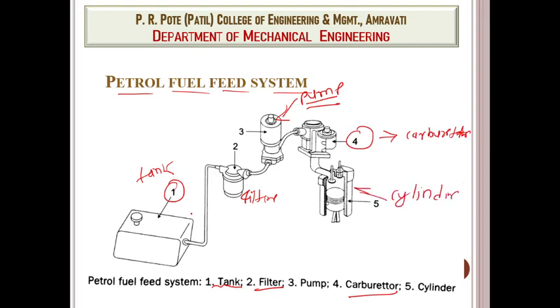So in this way, the fuel is transferred from the tank. The fuel is filtered, then passes to the pump, which increases the pressure, then the fuel passes into the carburetor, and from the carburetor it enters the cylinder for combustion through this inlet valve, guys.